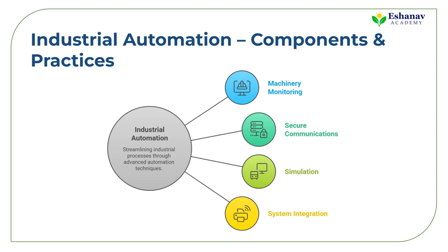Industrial IoT emphasizes monitoring, predictive maintenance, and real-time decision-making. ESP32 nodes equipped with vibration and temperature sensors can send alerts when thresholds exceed limits, preventing costly machine failures. Challenges include harsh environments, integration with legacy systems, and strict uptime requirements. Best practices involve using industrial-grade sensors, secure MQTT communication over TLS, and simulating high-load conditions before deployment.